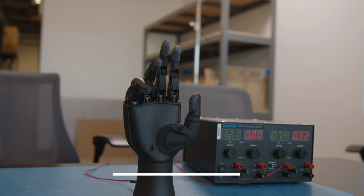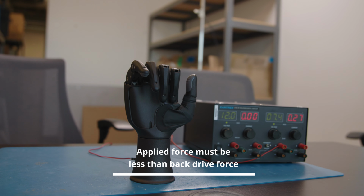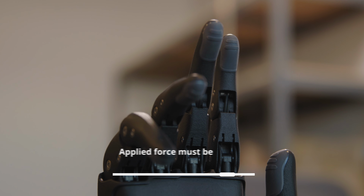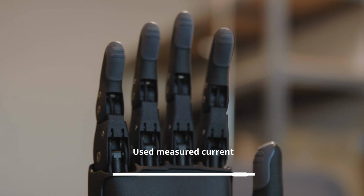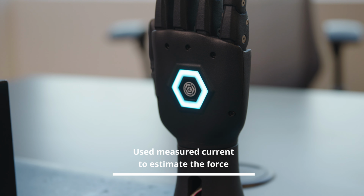For the limit switch to function on the S-type actuators, the applied force must be less than the backdrive force given on the datasheet. If that looks okay, check your mechanism and linkages to make sure they're not preventing the actuator from reaching full travel. You can use your measured current to estimate the force from the current versus force chart on the actuator datasheet.